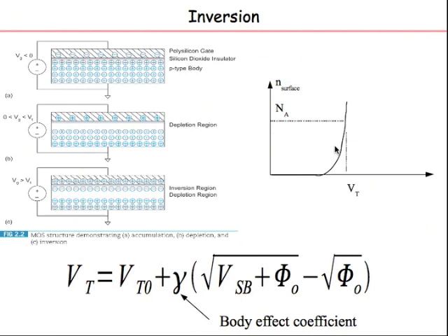At 300 millivolts, you have 1000. At 400 millivolts, you have a 10,000 difference in the concentration between strong inversion and the voltage less than that. So at some level, you can say that Vt is like a threshold, which is why it's called the threshold voltage, below which the transistor conductance is very poor, so it's off, and above it, it is on.